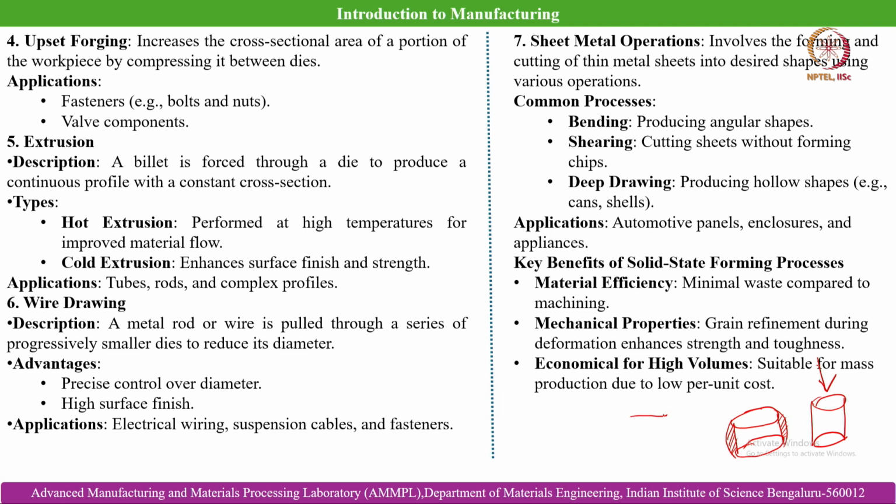So, what we basically do in case of an extrusion die, if there is a metal piece being extruded through this opening, and the metal piece after being extruded goes in the direction of the application of the force, then we call it forward extrusion. In the other case, if the ram which is applying pressure is hollow, with a concentric hole in the ram, then the metal piece can go in the opposite direction of the ram movement. Then we call it backward extrusion.